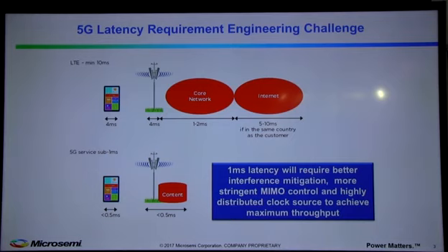This will be solved by adding bandwidth and adding connections to the mobile phone at the edge of the network. Also by changing the frame structure of the RF in the 5G environment. So the frame will become, instead of 1 millisecond frame, it will go to a sub-millisecond frame. And the content will be accessed in less than a millisecond.